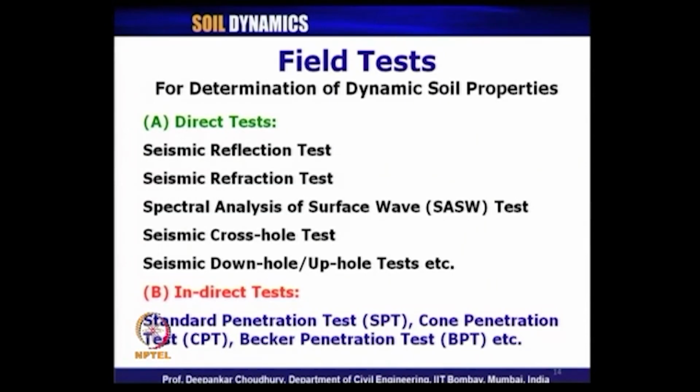One is seismic reflection test, another one is seismic refraction test, another one is spectral analysis of surface wave test, which is in short called SASW. If you look here: spectral, S; analysis, A; surface, S; wave, W. So, SASW test, and a modified version of this SASW test is also available nowadays, that is called MASW.